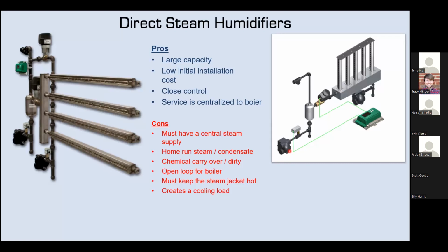Let's say you have a set of these on different ORs in a hospital. Then you're just really worrying about accessing the boiler for service and not looking in the ceiling above the operating room, which cuts down on the number of operations that they can do. And for getting into that space, you need all sorts of protective gear and to suit up, and it can be a pain. So you'd rather have something that you don't want to touch in that kind of space.